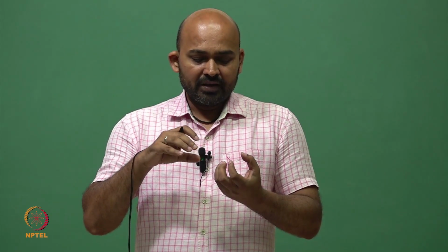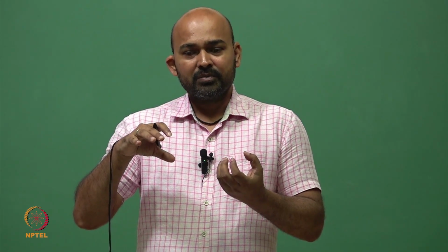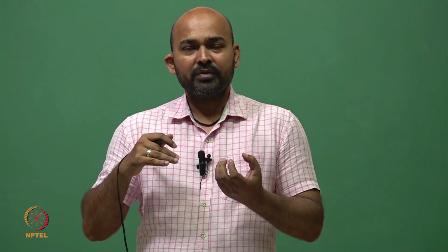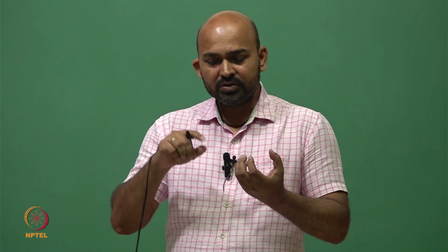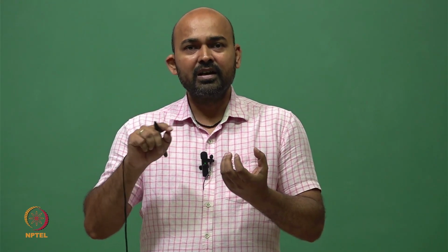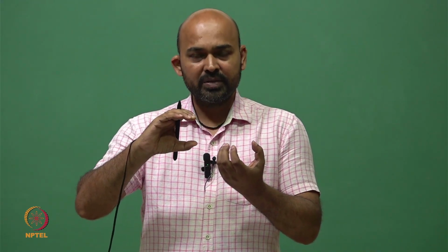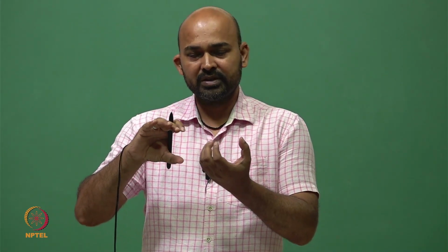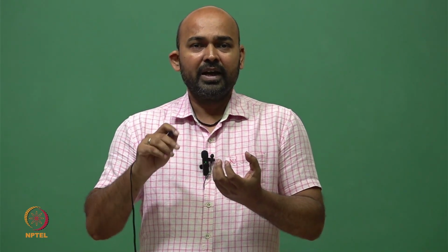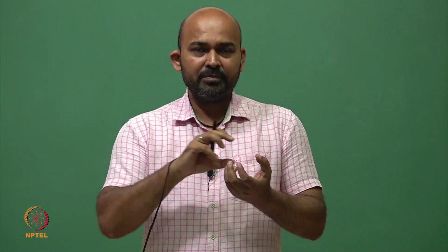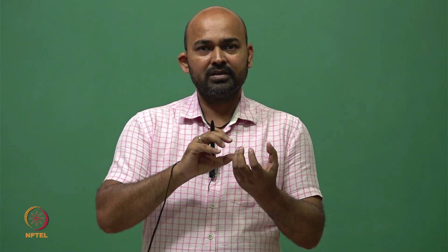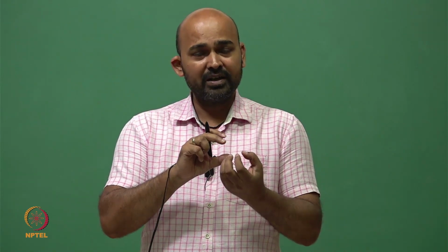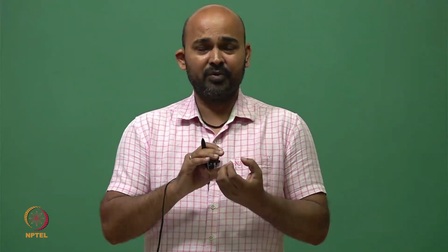Now if this electrical motor needs to shut off, we suddenly turn it off, then because of the parasitic inductance, there is a very high voltage buildup at the input of this second stage, the motor, and this high voltage can impact this microcontroller which is running at very low voltages, for example 5 volt or so.